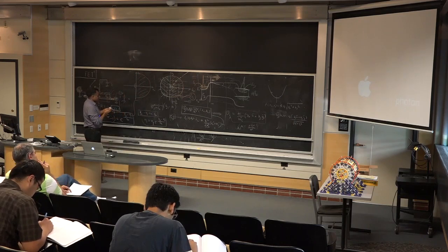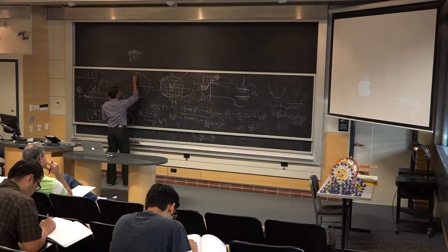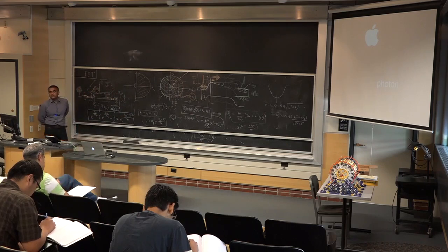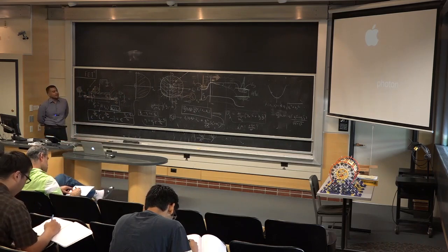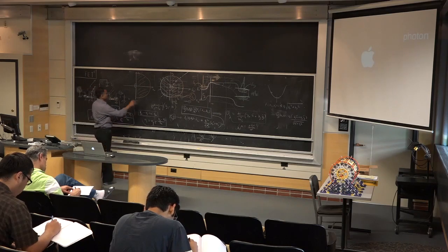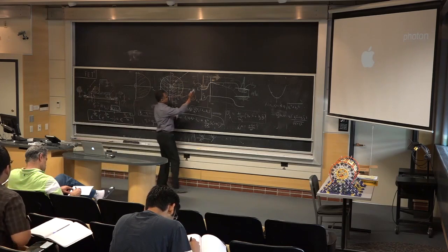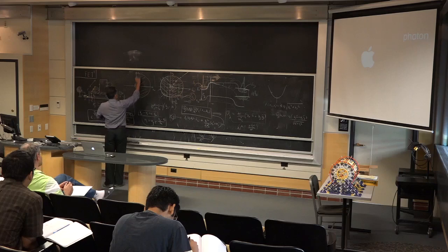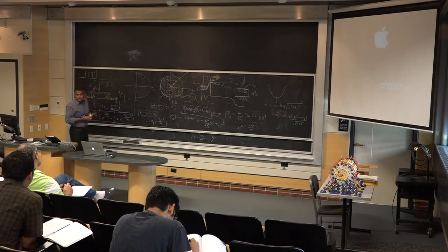And the initial situation was this dashed line here. And now you have a redistribution of the occupation function in K space. It's just a redistribution. Does that make sense? At least what we are trying to claim is the gate is in complete control of the charge at the source injection point. And the moment you do that, now we are ready to write the answer down of how much current is going to flow and all that stuff.